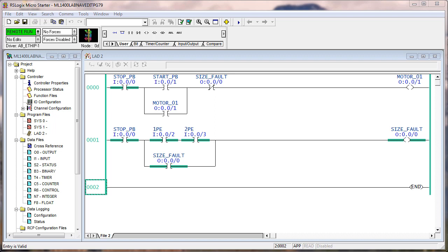When you press and release the stop button while the photo eyes were still blocked, did the red light extinguish? No. Why? The carton's not removed. Is this a good thing? Yes. Why? Forces removal of the rogue carton. Then turn off 1 and 2 PE. Did the conveyor restart? No. Is this a good thing? And again, yes. It's a safety issue.